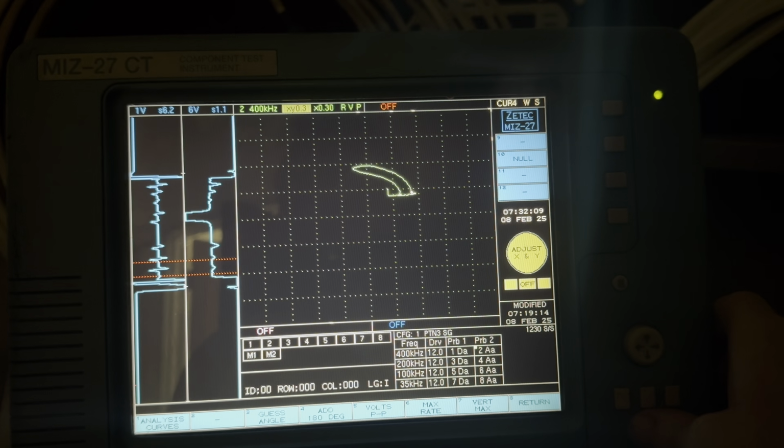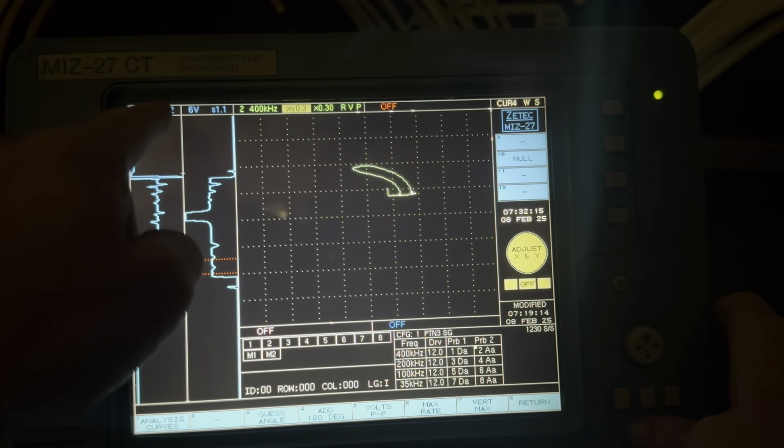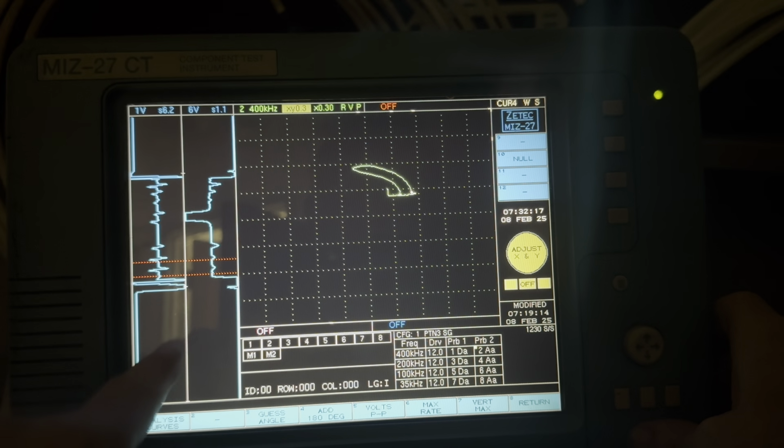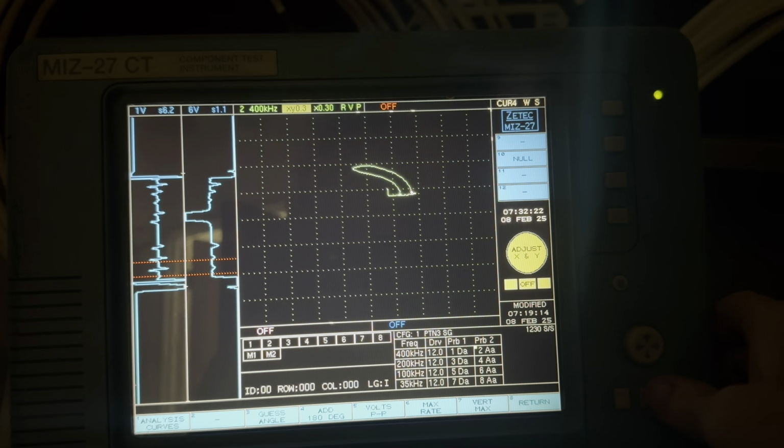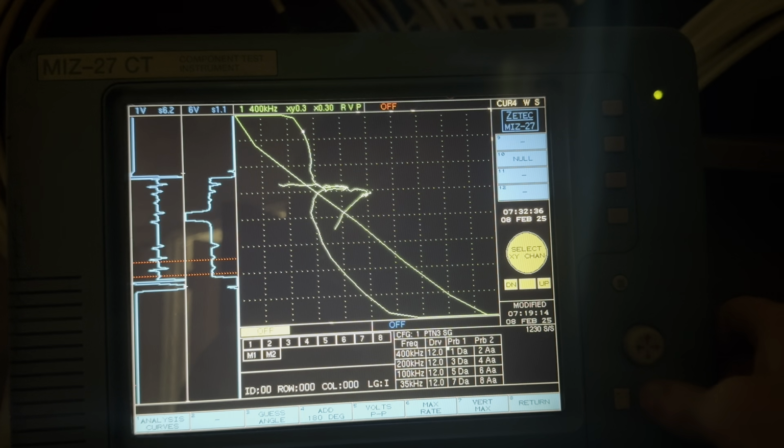And when we configure it this way, if you have a long gradual wear, for example, in your tube, you'll get a long gradual shift or drift on an absolute strip chart. Differential arrangements, which were channels 1, 3, and 5, are better for short flaws like short axial cracks, short pits, because it's comparing one area of the material to the other simultaneously, okay?